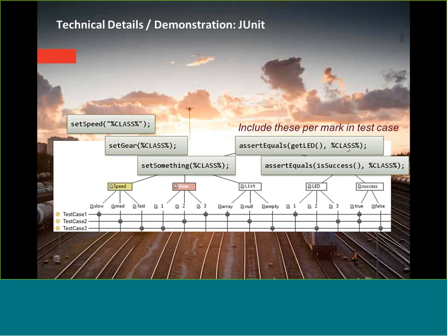And we then compare it against the selection we had in the classes. So for the first test case, we would assume that the first LED is then turned on and the test was successful. The second, we expect the third LED to be turned on and the test was successful. In the last test case, we have the LED number 2, and we consider that something went wrong so that this assertion does not hold.